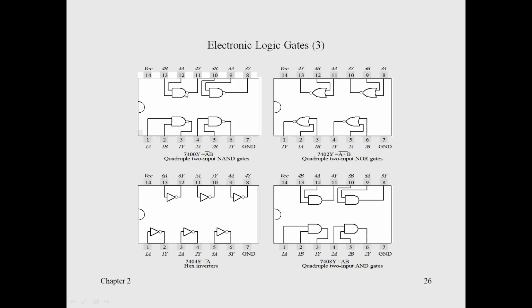Okay, so if it's a NAND gate, you see this is basically ASIC ICs. And 7400, this is the 74 series. So 7400 is a quadruple 2 input NAND gate. In that, pin number 1, pin number 2, and you remember one thing: wherever there is a notch, below that notch there will be pin number 1. So keep this in mind: pin number 1 and pin number 2 are the input of the first gate, and 3 is the output. So 1 and 2 input, 3 output. Second gate, 4, 5 input, 6 output. 7 is ground, 14 is VCC. And in this way the arrangement is done.